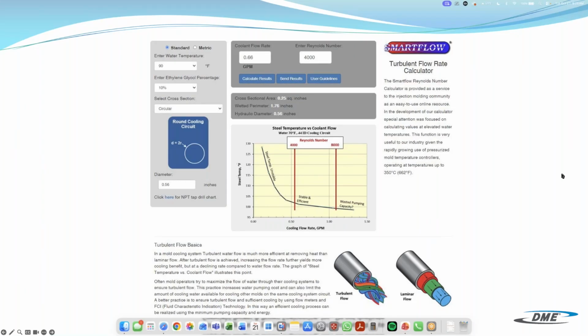Okay. We have a question about scale. Would it be best to have the supply water softened or perhaps reverse osmosis water to give a much better quality of water in the first instance? Yeah, I mean, anything you can do to give yourself the best opportunity to prevent scaling, yes. But then, adding chemicals and having the water treated is always good, but then you also don't want to go too far either, because then that's going to cause potential issues with pumps and seals. So it's just finding a good balance.